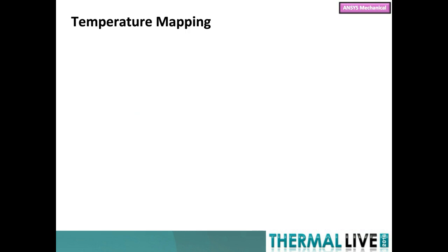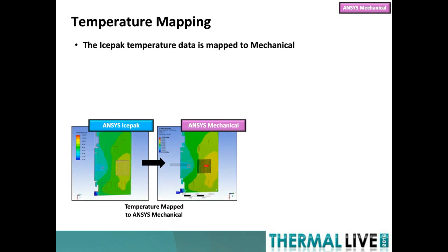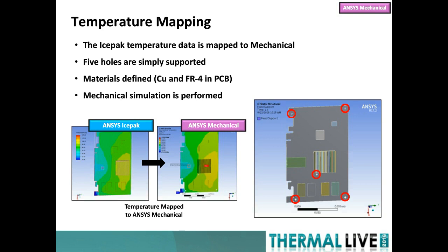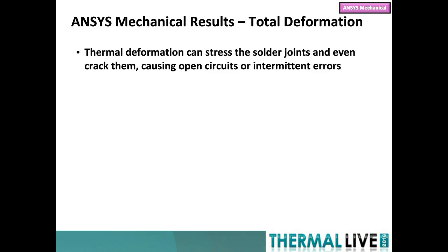The IcePack temperature data is mapped into Mechanical. For the sample case, 5 holes were simply supported. Materials were defined, and the mechanical simulation was performed. Thermal deformation can stress the solder joints and even crack them, causing open circuits or intermittent errors.